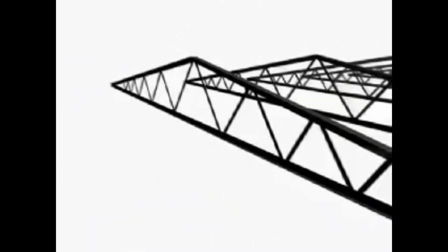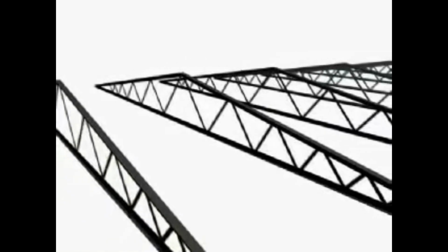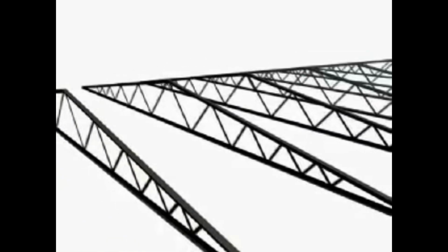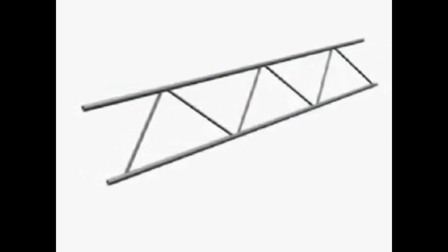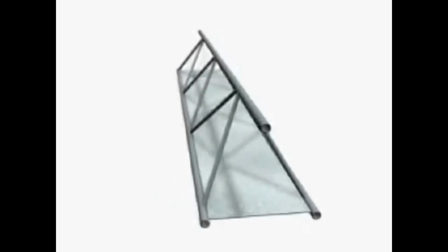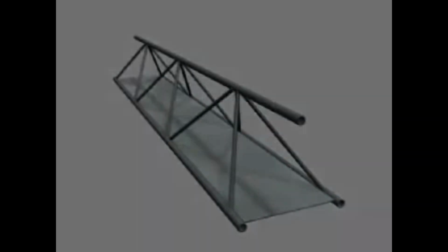Steel trusses are highly efficient structural forms, able to span considerable distances. They are visually light and services can pass through them. Trusses may be fabricated from a variety of steel sections, including circular, square and rectangular hollow sections, angles, flats, rods and cold-formed profiles. Trusses may be 2- or 3-dimensional. 3-dimensional structures comprise of triangular cross-sections or occasionally rectangular cross-sections to accommodate walkways or building services.